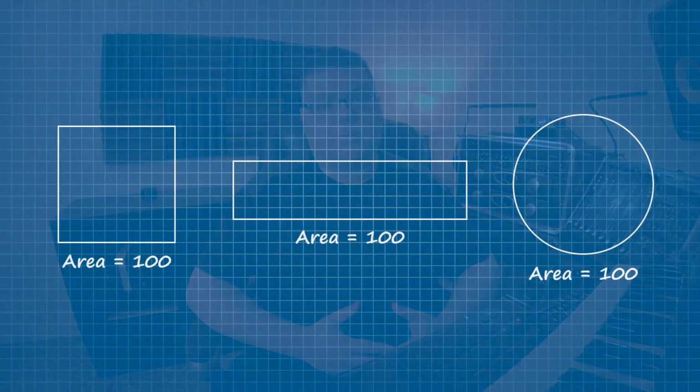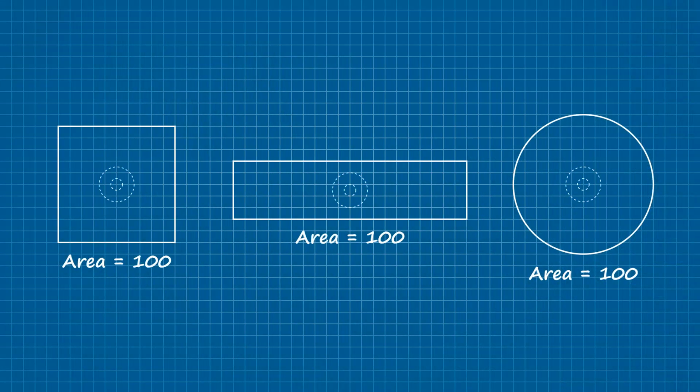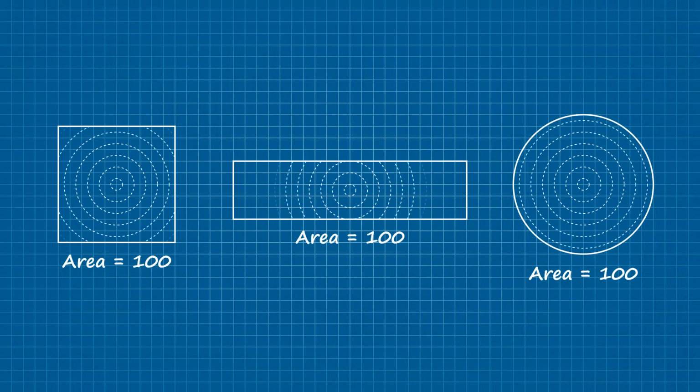their similarities go. When a fluid, such as air, flows through one of these, peak velocity is achieved around the center. And as we move away from the center, there is a drop in velocity because of the air dragging against the vent itself. So the smaller the circumference for any given vent area, the more efficient or lower drag that vent becomes. And bearing that in mind, let's have another look at our three shapes.